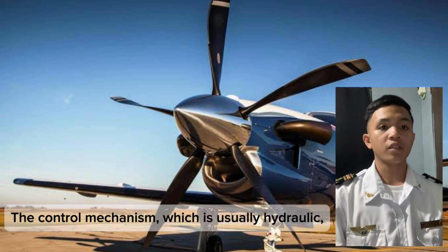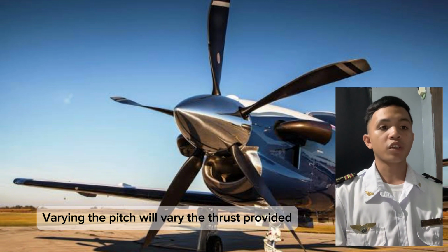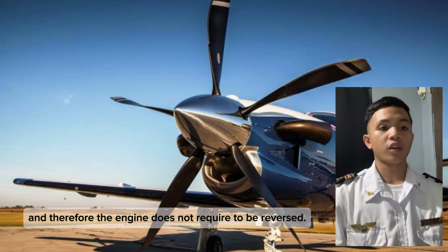The control mechanism, which is usually hydraulic, passes through the tail shaft and operation is usually from the bridge. Varying the pitch will vary the thrust provided, and since a zero pitch position exists, the engine shaft may turn continuously. The blades may rotate to provide astern thrust, and therefore the engine does not require to be reversed.